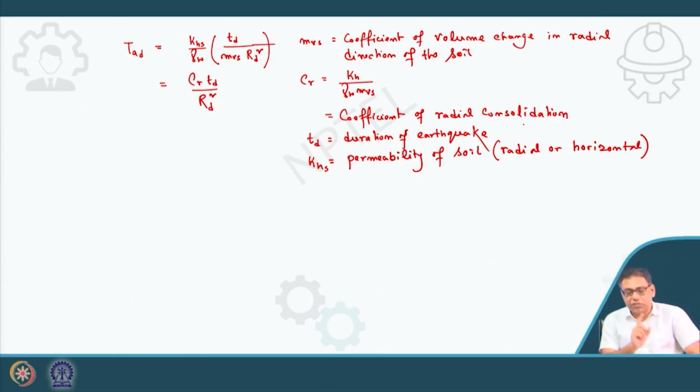So what are the things we should incorporate in this study? We should incorporate the permeability of the column, because it is obviously more than that of the soil, it is not infinite. Then the stiffness effect of the column is not incorporated in this analysis, so there is a need to incorporate the stiffness effect or compressibility of the column.